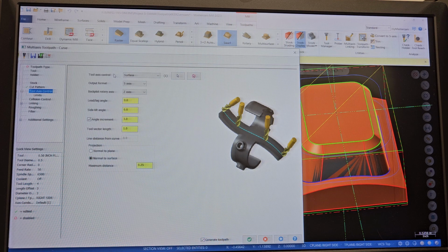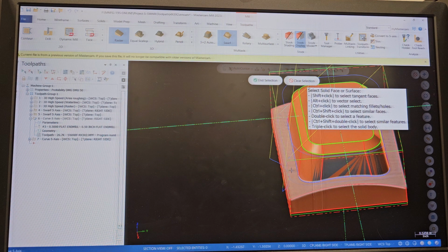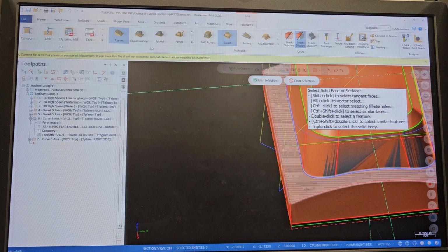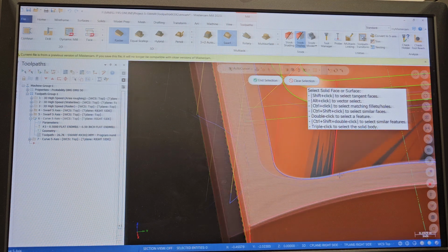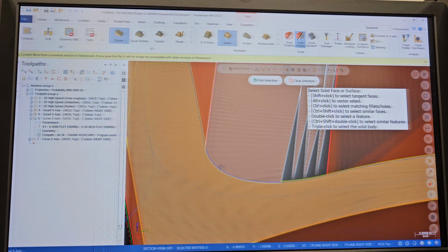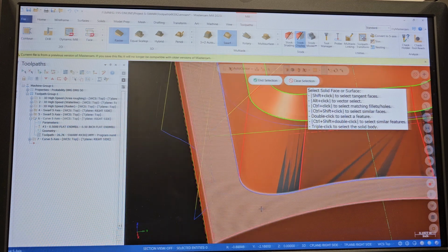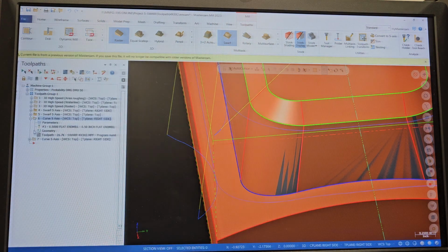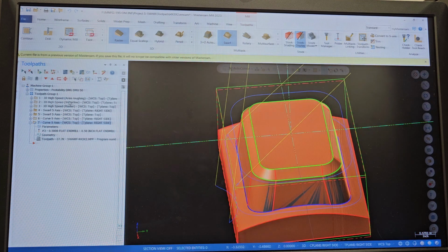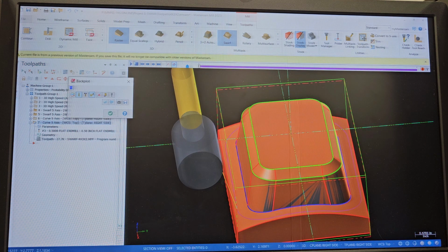And the tool axis control is gonna be to the surface, and that's gonna be this surface right there. So the curve toolpath is gonna clean up this little leftover with a flat angle, it's gonna make it nice and smooth. This is the same, you don't need to worry about it, it's the same curve toolpath, I just do it twice.